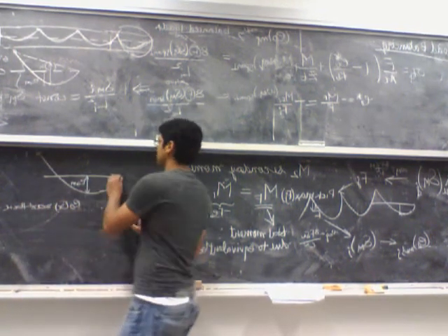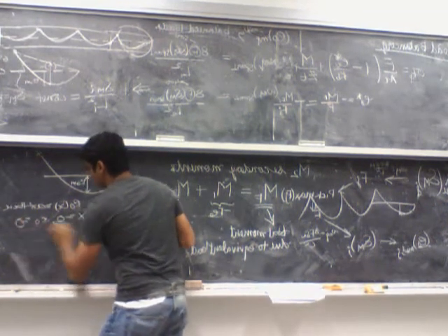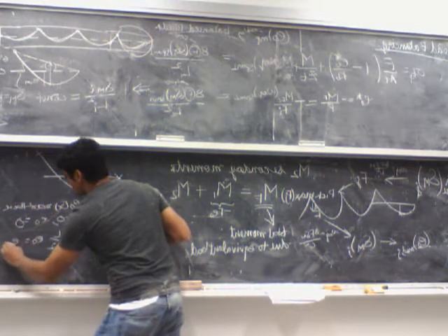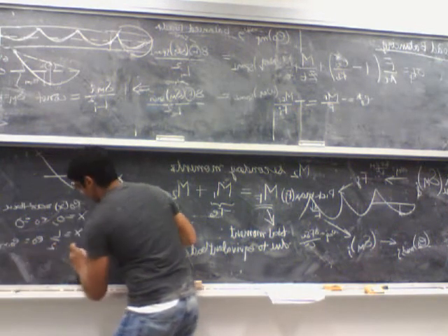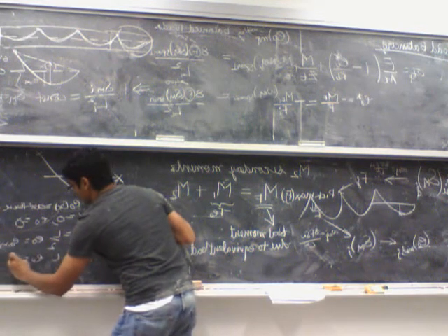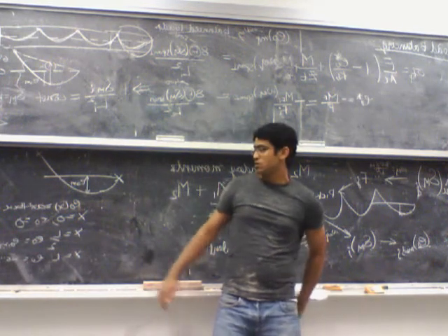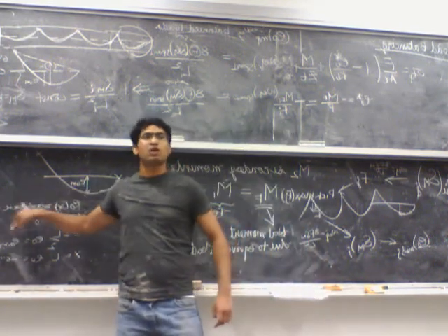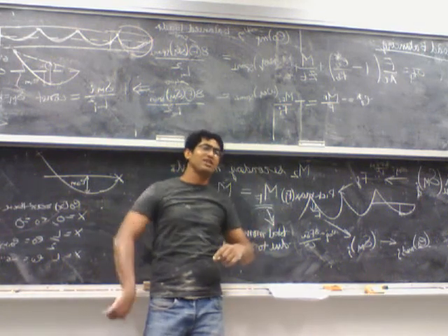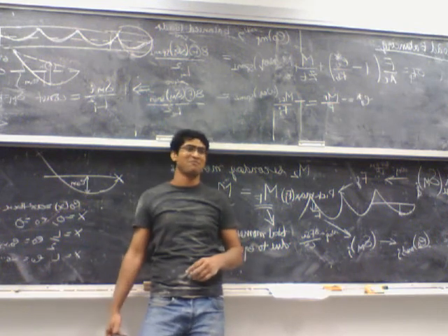I need 3 equations. This is my first equation. At x equal to 0, E naught equal to 0. At x equal to L over 2, my E naught is, let's say, E naught M, and at x equal to L, my E naught is whatever, minus 6 inches or minus 5 inches, whatever you have fixed. So you get 3 equations in a, b, and c. You solve for a, b, and c. You get the actual equation for the tendon. You differentiate the equation. You get the location of the maximum. You find the maximum. Make sure it's less than E naught MP.